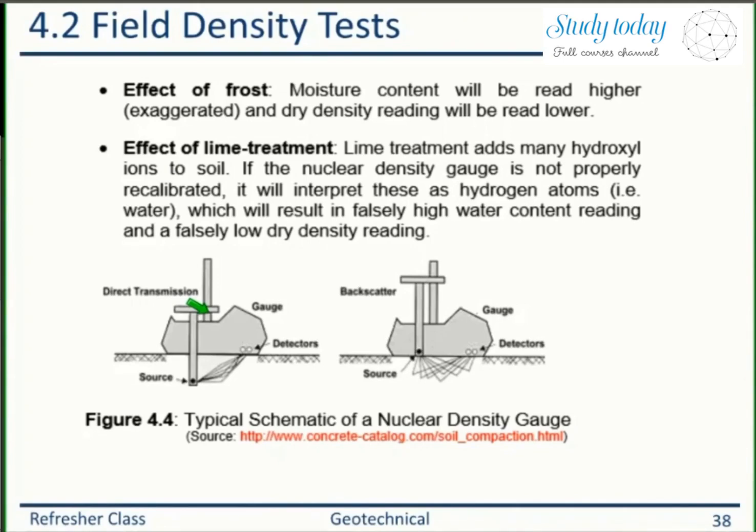Yes, Luis, more or less the nuke test is standard now, but it used to be the sand cone test, among other methods earlier, so it's better to know that also. But I do agree, it is more speedy, right? You would not hold the contractor on the job to do your test, because this is very speedy and you can do many tests repetitively. That's why the nuclear density gauge is in practice these days. Totally agree.